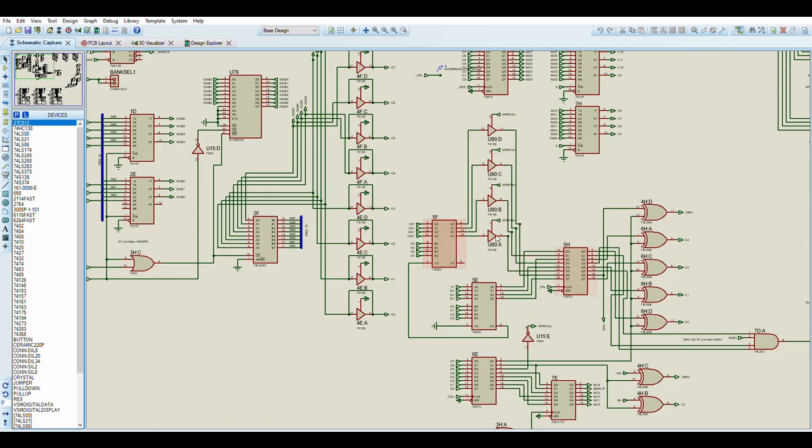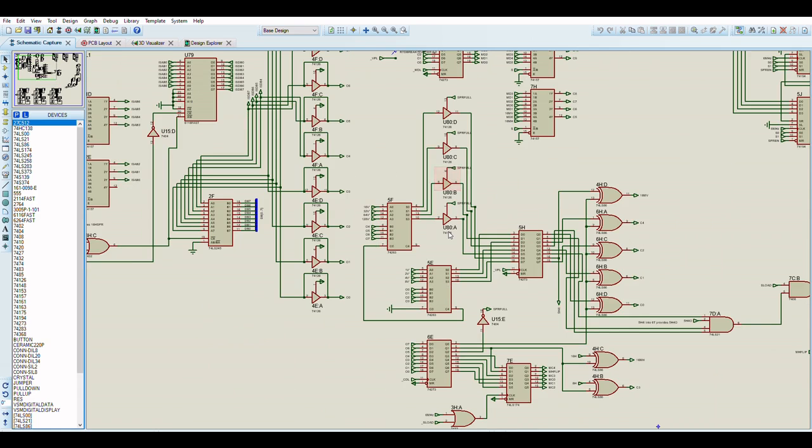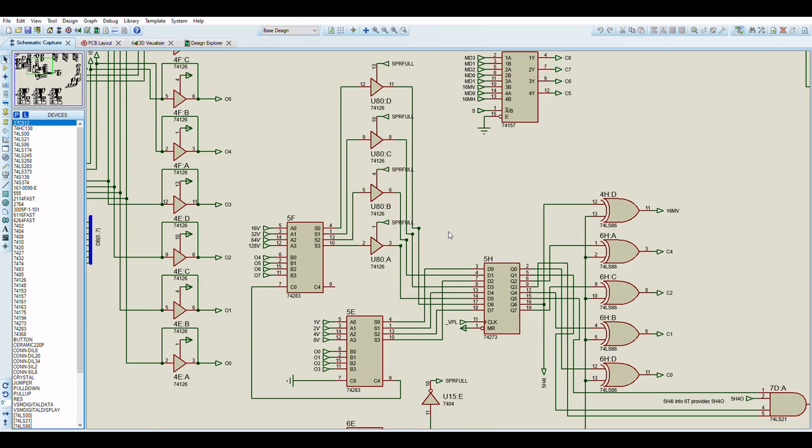How it decides to start rendering a sprite is really quite interesting logic. It takes the vertical screen position, the scan line that it's currently rendering, and it adds it to the sprite position.